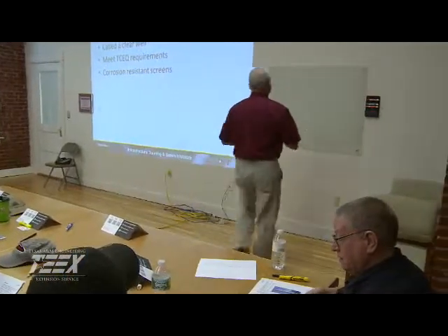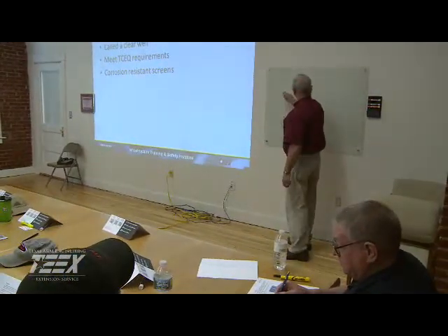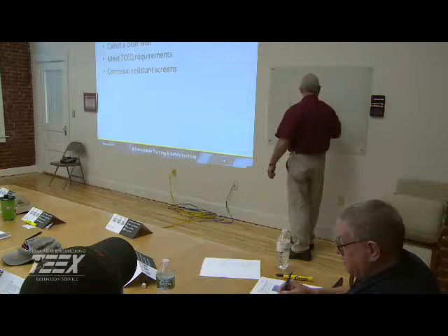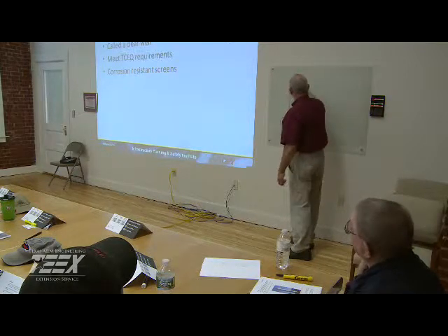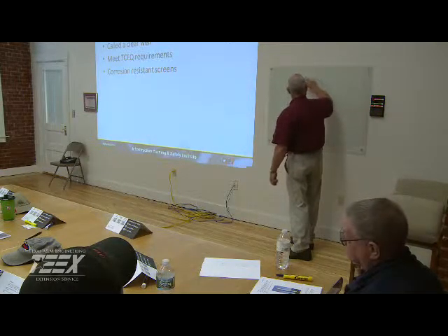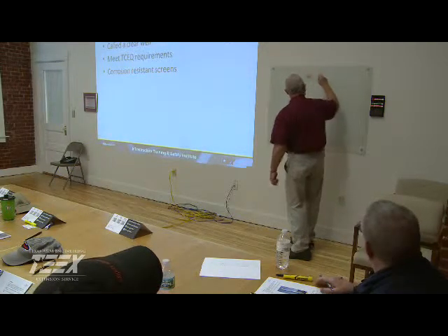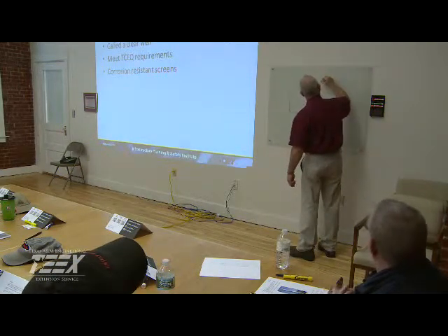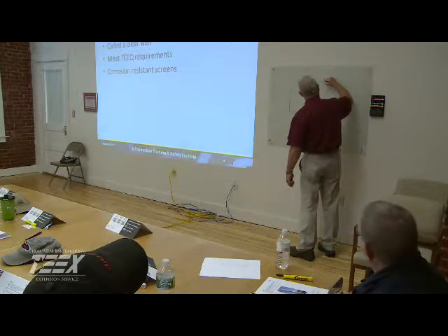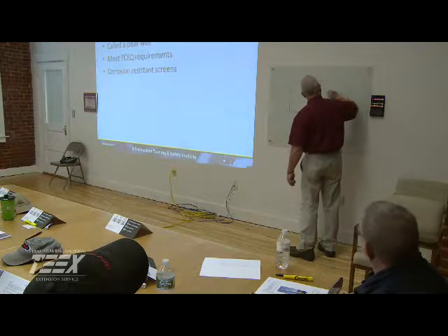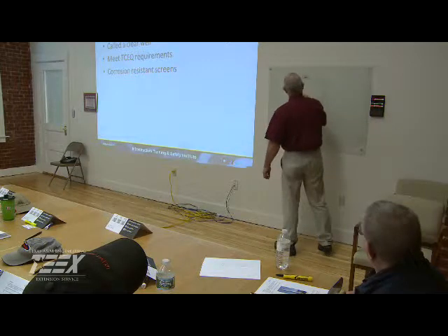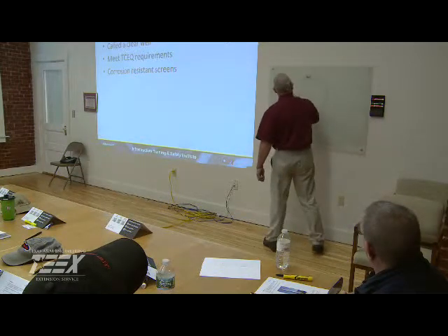It shows up. Now, when you're designing a tank, let's say it's going to be a ground storage tank, and we're going to have our vent up here and our screen on here, and then might have a roof hatch and a lid, and then we're going to have a ladder over here, and then I'm going to have my overflow.